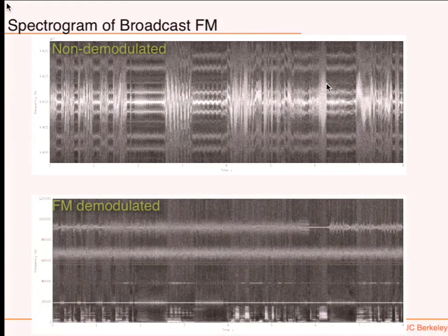Then you're going to FM demodulate it. Because everything is now in digital form, all you need to look at is the change of phase with time. What is frequency? It's the change of phase over time, the derivative of phase over time. It's really easy to look at the phase because everything is complex and digital, so it's no problem. You're going to take the derivative of the phase and demodulate the FM signal, just by computing finite derivatives by finite differences.